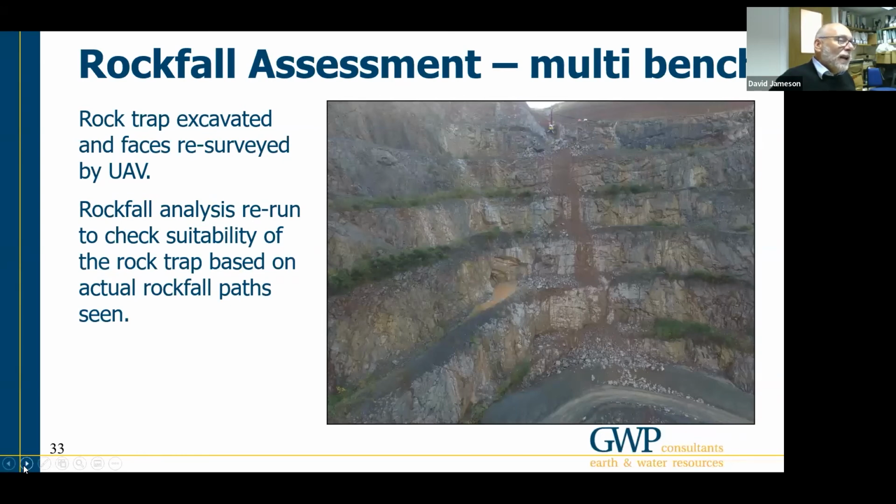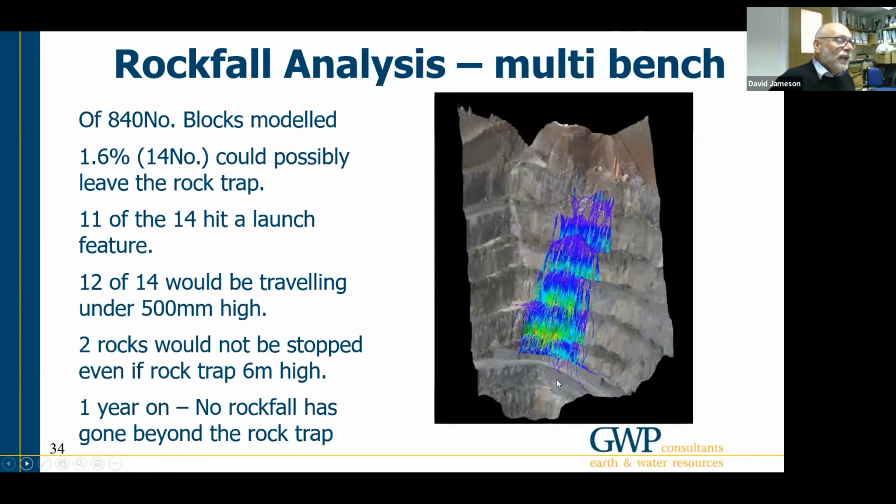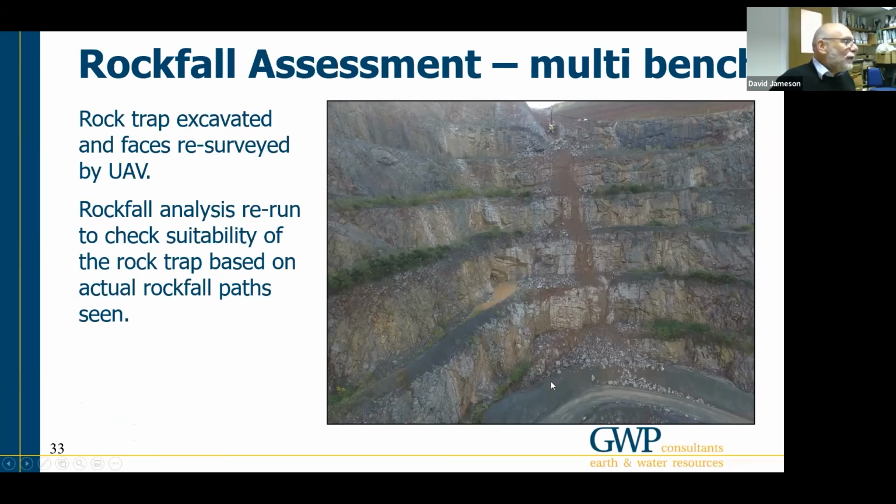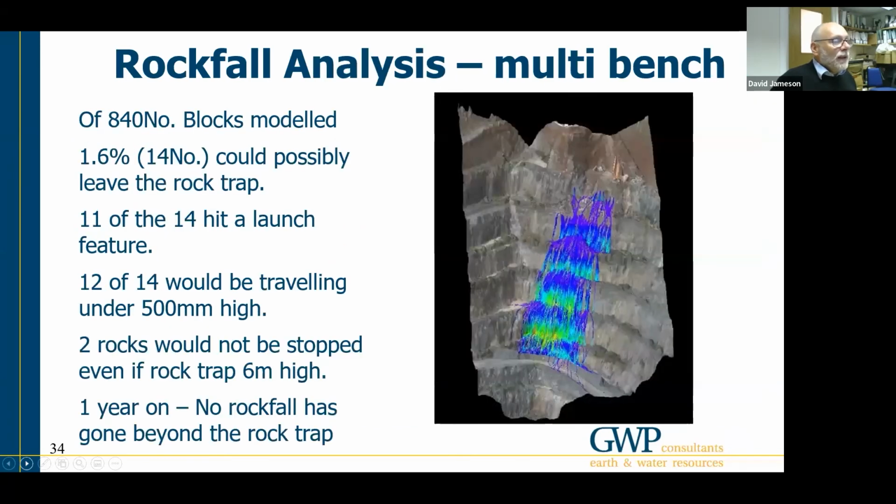So once we'd finished all of the breakthrough from the slot, the bottom of all of this material in the rock behind the rock trap was dug out and cleaned out, and then we resurveyed that slot area, so we got a good understanding of the geometries of the debris piles which have been forming on each of the benches. So we could then rerun the analyses and adjust the rockfall protection at the bottom.